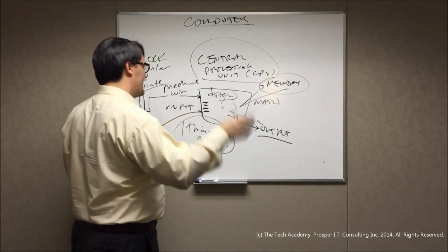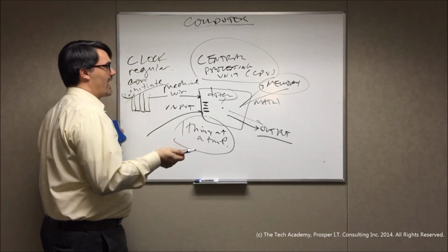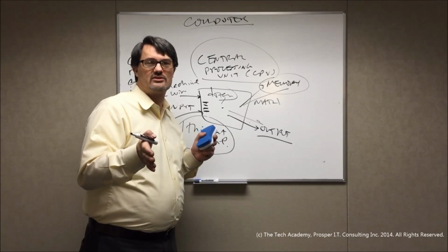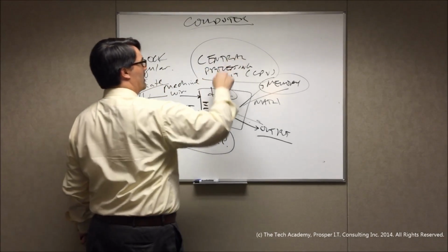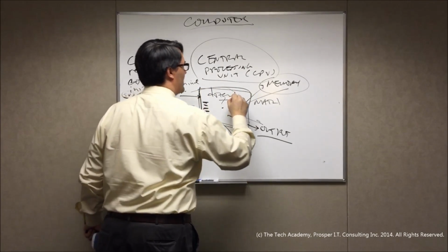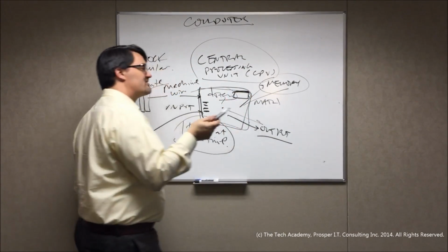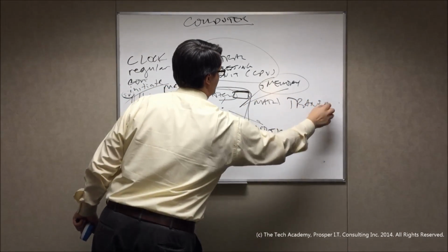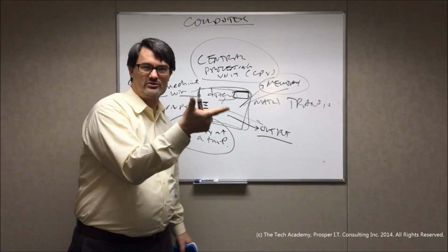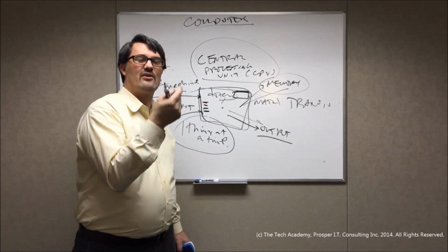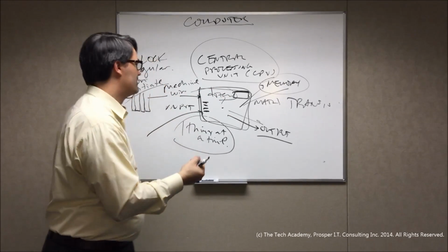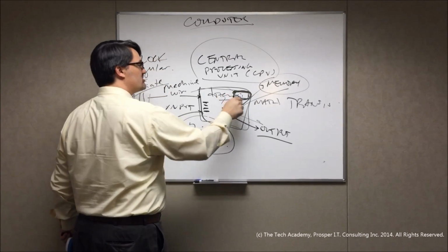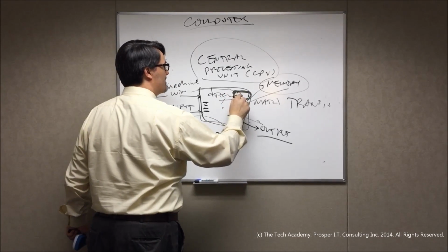And every single time it hits the central processing unit, it says, okay, what's the next thing I have to do? Well, how does it do that? On this central processing unit board will be a tiny chip, a tiny piece of memory. And all it is is transistors. They remember whether they're equal to 1 or 0. They remember whether they actually have 5 volts on the output or 0 volts on the output. So there's all this memory in here. And one of these little pieces of memory, its job is to store the very next instruction to be run.